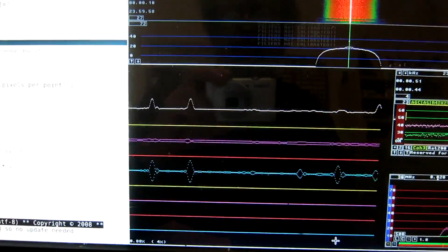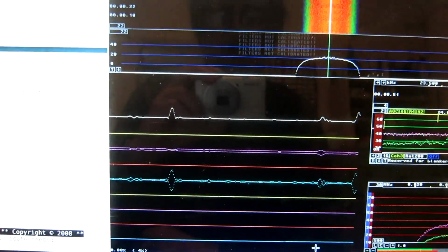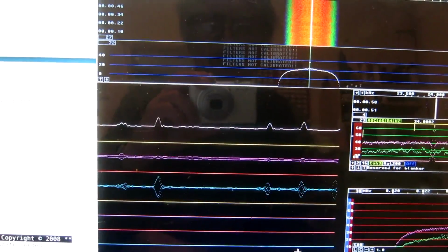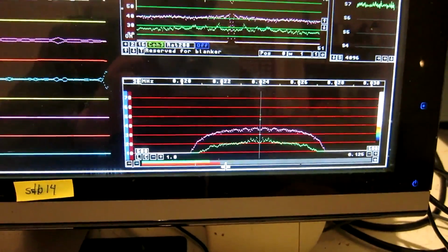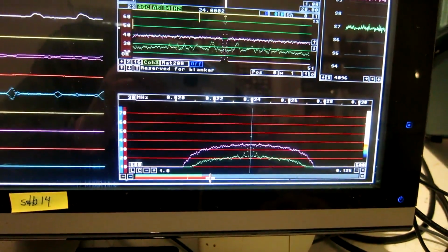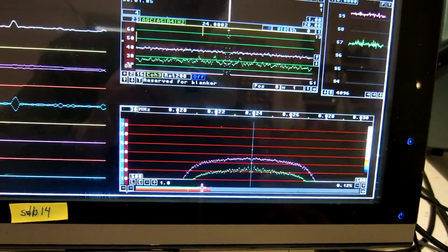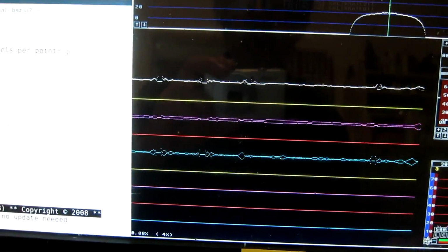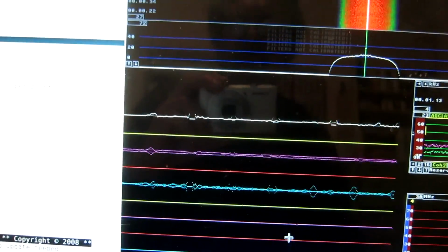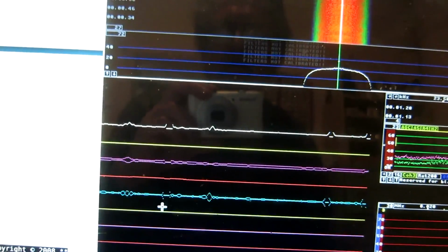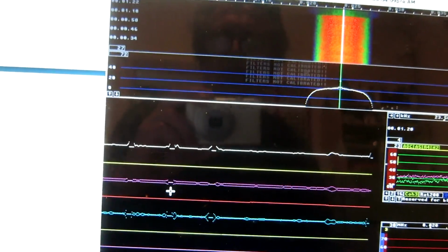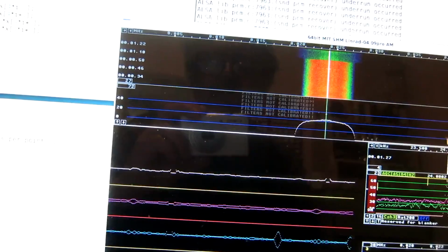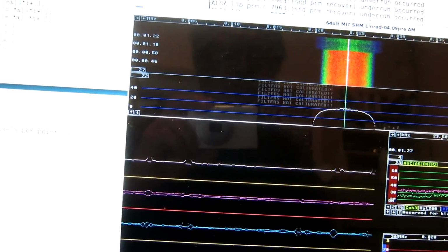I have increased the level of the orthogonal channel, that's where the pulses are, by a factor of 5, that's 14 dB. And now the noise floor with the pulses has a similar level as the AM stations plus the pulses. If I now enable the blanker, you see here, you can see that we cut holes at the right positions with some improved precision, although, as you can see here, it's not quite perfect, or let's say quite a bit from perfect.